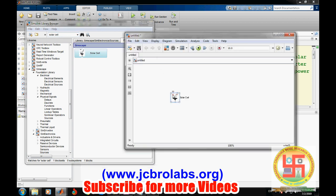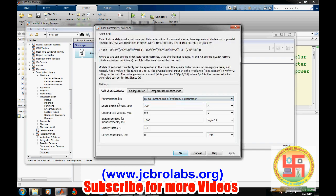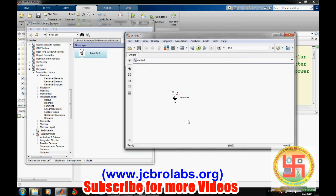Alright, so double click on it, and you will find it is represented by the short circuit current, as I mentioned, the open circuit voltage, and the irradiance at 1000 watt per meter square. We were getting these values and the quality factor. Similarly, from here you can change the model by equivalent circuit parameter 5 parameter model or the 8 parameter model, or by short circuit output current voltage of 5 parameter model. So you can change this particular model by any means, and then you apply and then OK.